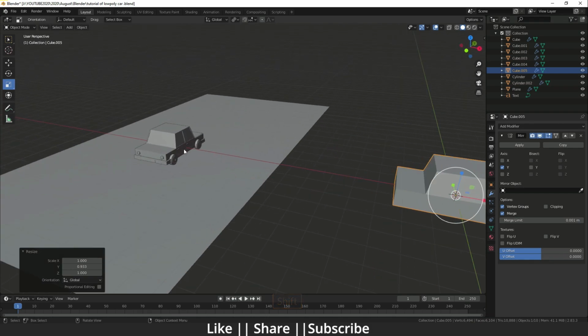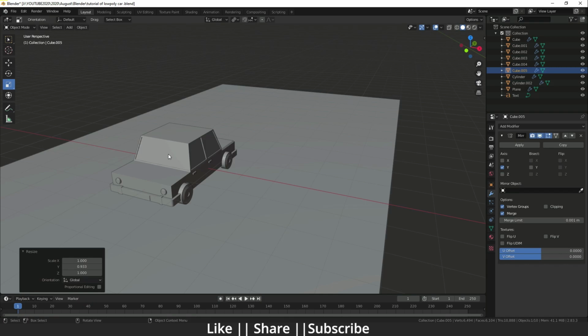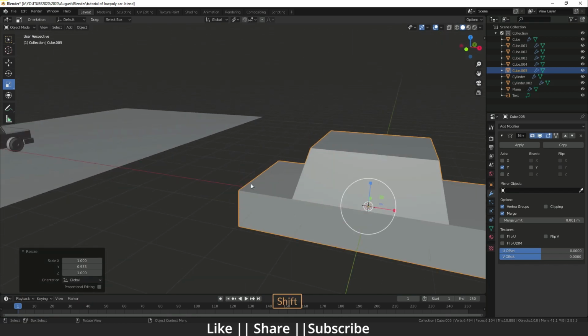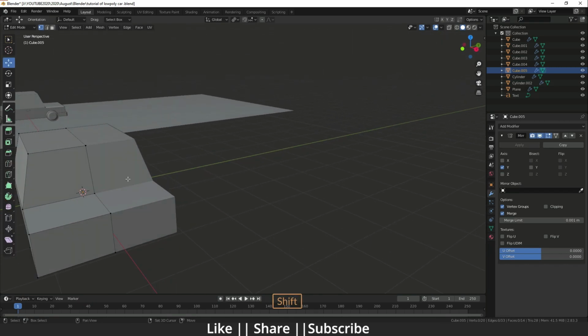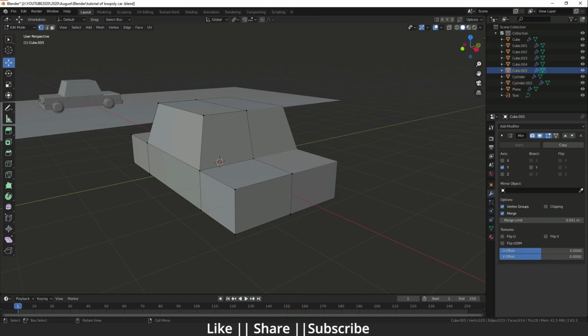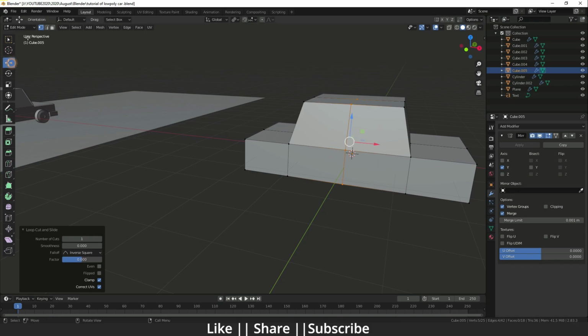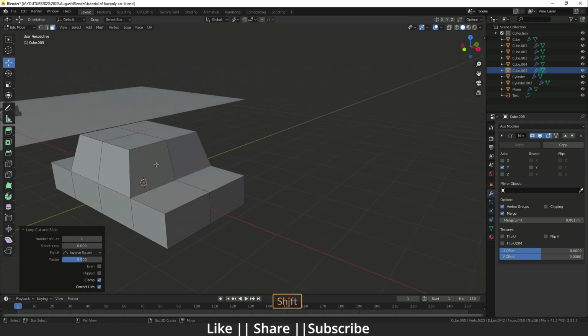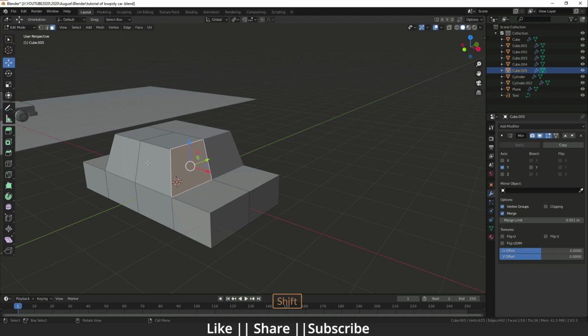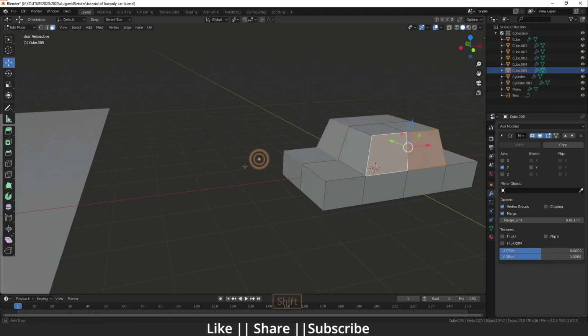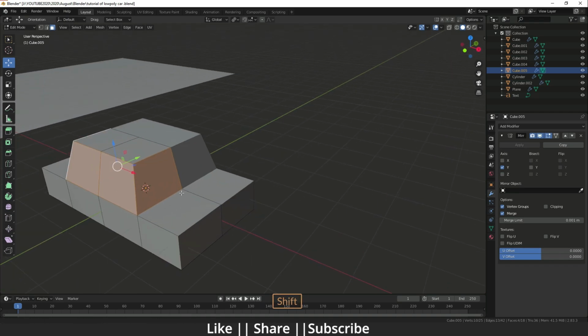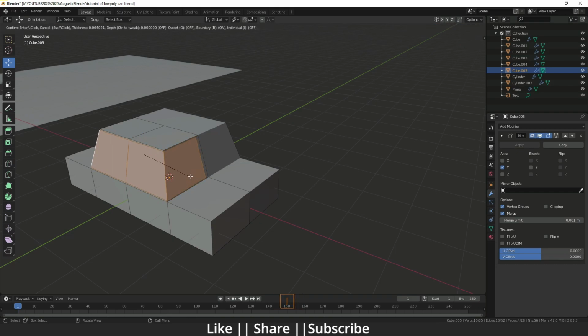So now I'm going to show you how you can make the glass. For that what you have to do is add one edge here like that. And after that go to face mode and select that face, that also, and that also. And you can do insert, but when you do the insert, here you can see it's inserting all of them at once, so we don't need it like that.